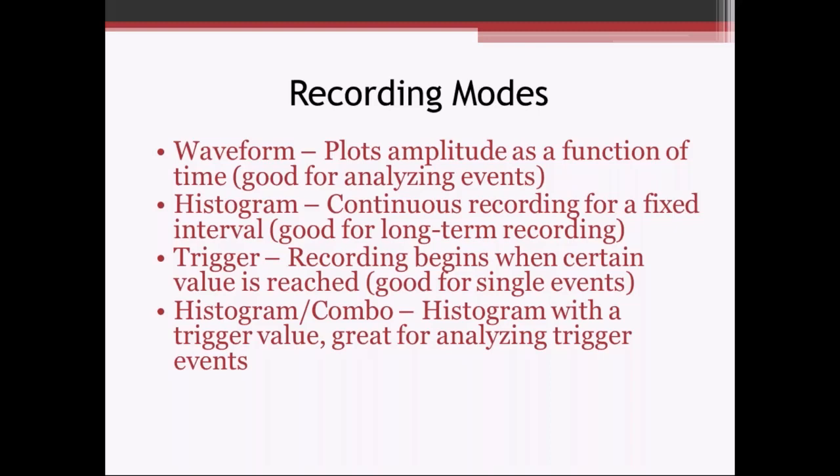Another recording mode is a trigger mode. I guess it's less of a recording mode, it's just an option to set a trigger value, and the recording will begin when that certain value is reached. So if you've got a threshold value of maybe 0.5 inches per second on a project, maybe you want to set that trigger at 0.25 or 0.35 to know if you're getting close to that 0.5 inch per second threshold that's set up on the project.